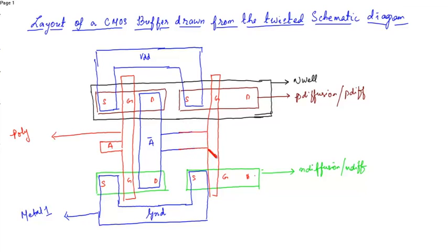So there is an overlapping between the metal and the poly layer. So we'll place a poly contact over here. So select the area, this portion in the Magic tool, and then place a poly contact.